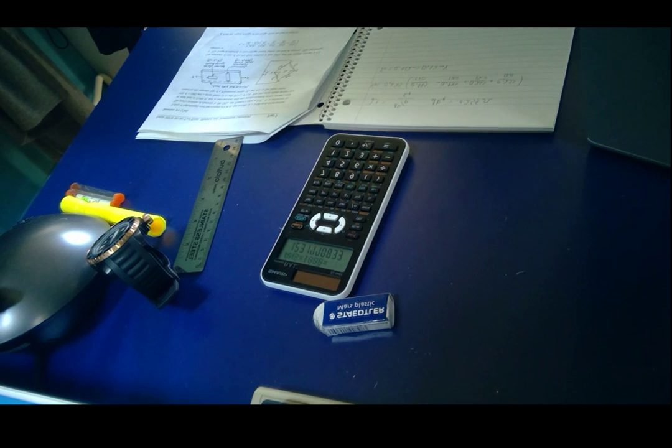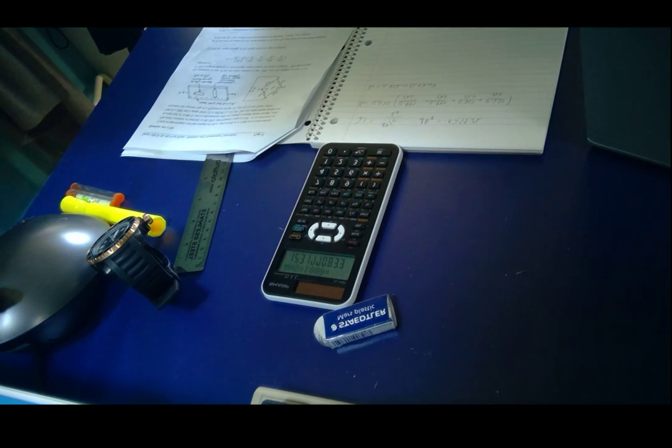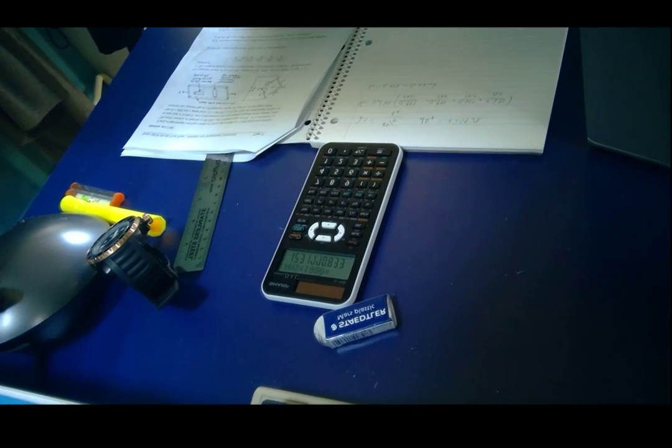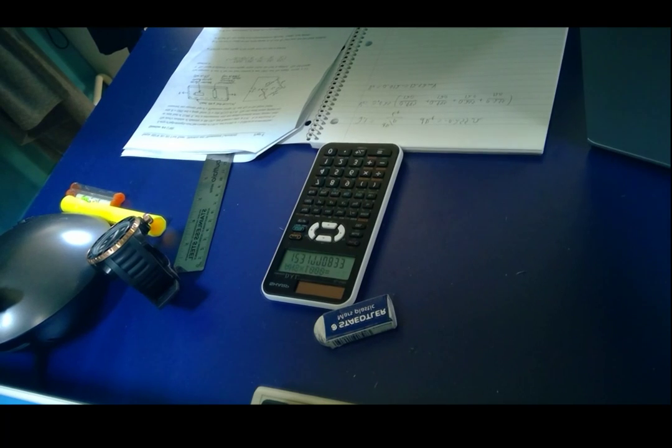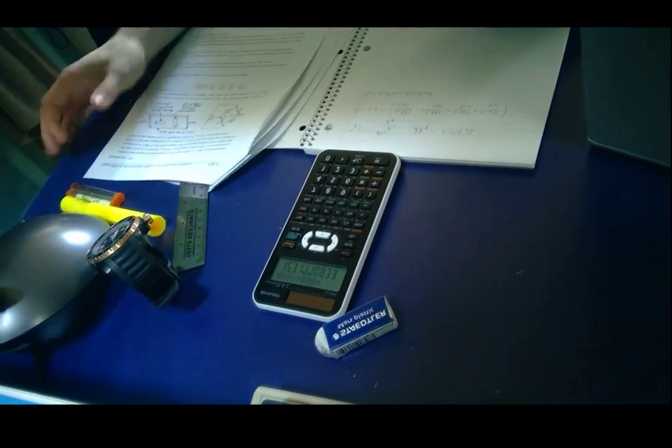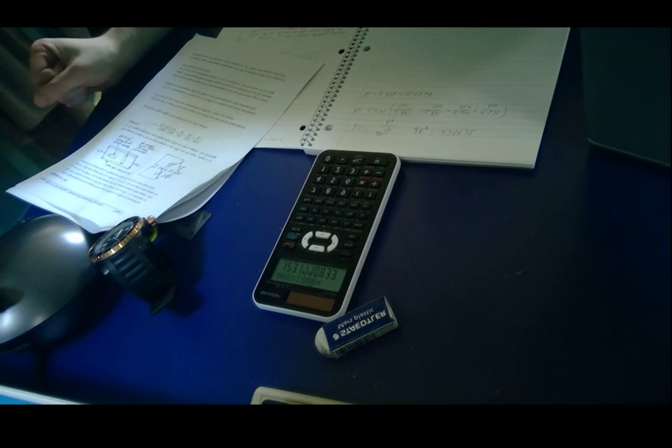The reason why is how the Wheatstone bridge works. Because R1 and R3 are always going to work together, and that's, by the way, the diagonals, meaning that they will have the same sign. And R2 and R4 are going to work together and have the same sign, and those two pairs have opposite signs. So when we use the transversely mounted strain gauges on the side that is opposite to what we were previously using, we're adding to our voltage. Now question E.